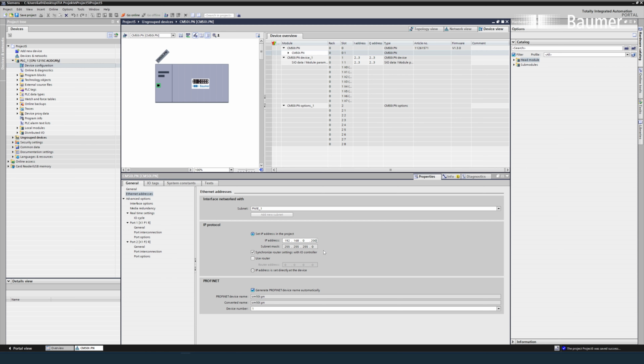And as you probably know, in Profinet networks, the Profinet device name is the actual identifier for the PLC to assign IP addresses. So the naming is pretty important. Since we only have one master here, we just set the name to whatever TIA decides for us, and we are done in this window. Now there's one more step we need to do.